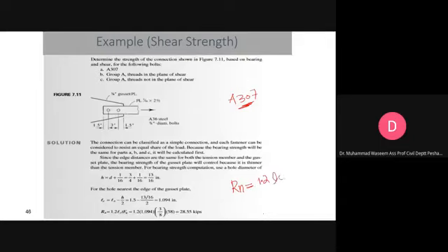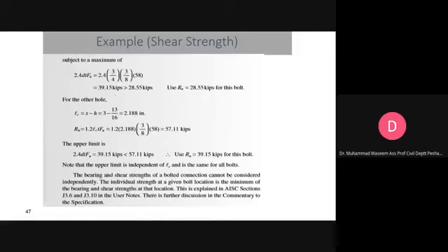You have to calculate the Lc, you have to know the thickness, and you have to know the material. They are made from A36 steel. Okay, A36 steel, we have Fu 58 ksi. Similar to the last problems, you can go through it. The procedure is similar. So you have to compute the bearing strength of the bolts. So bearing strength comes out to be